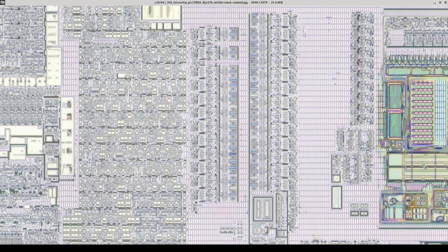In older generation devices, it was common to actually have dedicated NVM cells that were hardwired directly to the relevant logic. And so that's why these bit cells are so big. And again, we'll deep dive more into this later on. But these are enormous compared to the flash structures because they actually have the entire programming and readout circuitry separate for each bit, so it can parallel read all of these bits simultaneously.